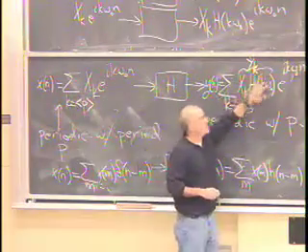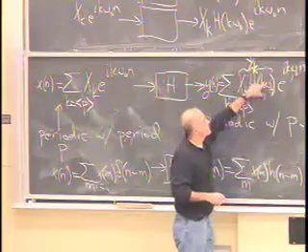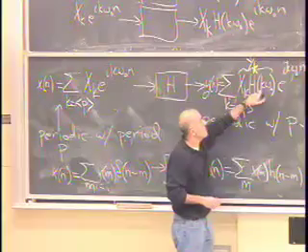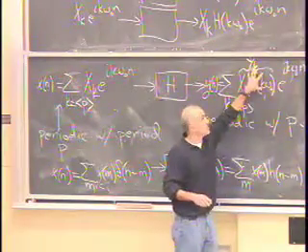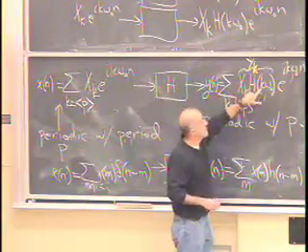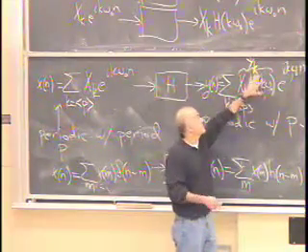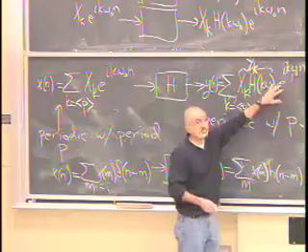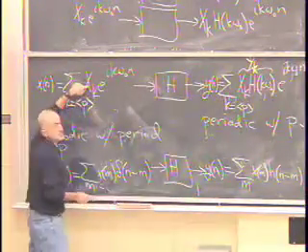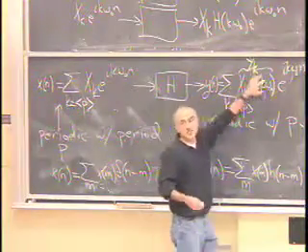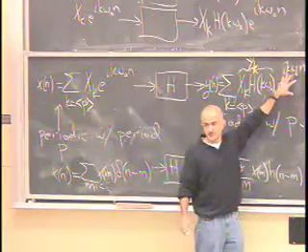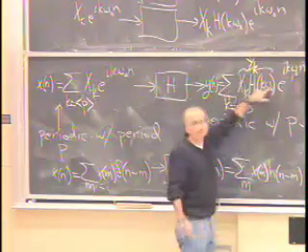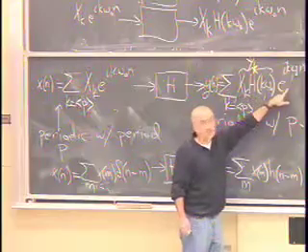At the output of the LTI system, each complex exponential gets scaled by the frequency response value at the frequency of that complex exponential. If the filter happens to kill the kth harmonic, then that harmonic is not going to show up in the output. If that harmonic didn't exist in the input, the corresponding xk would have been 0, so it wouldn't have popped up suddenly at the output anyway. So either of these two can ruin the party for this exponential.